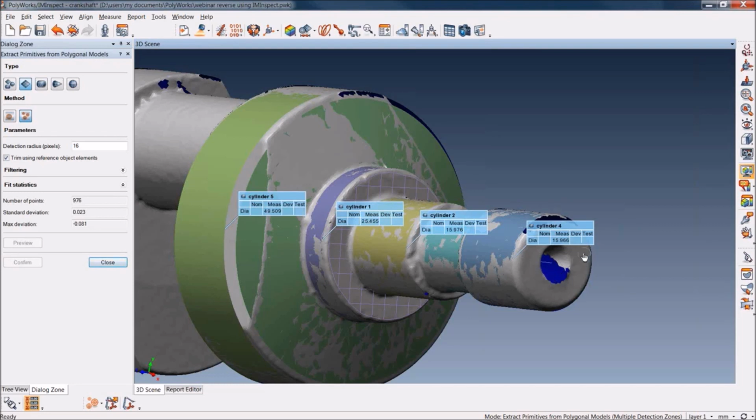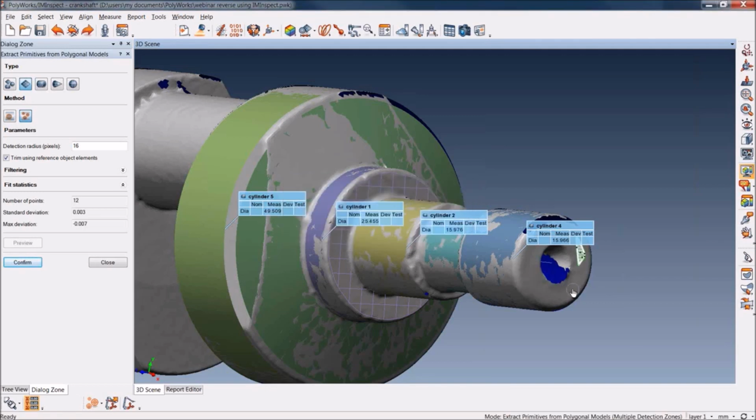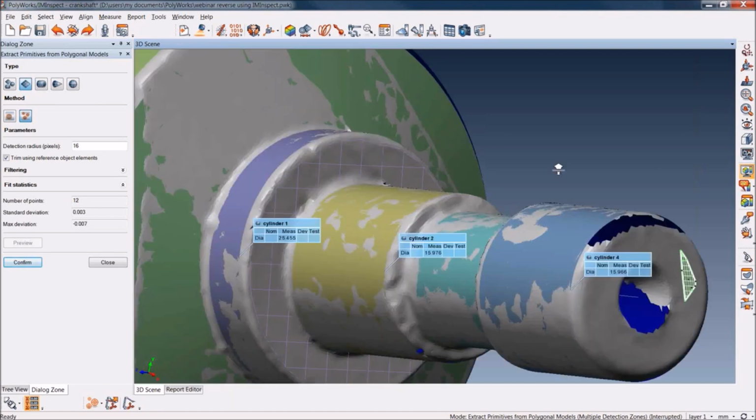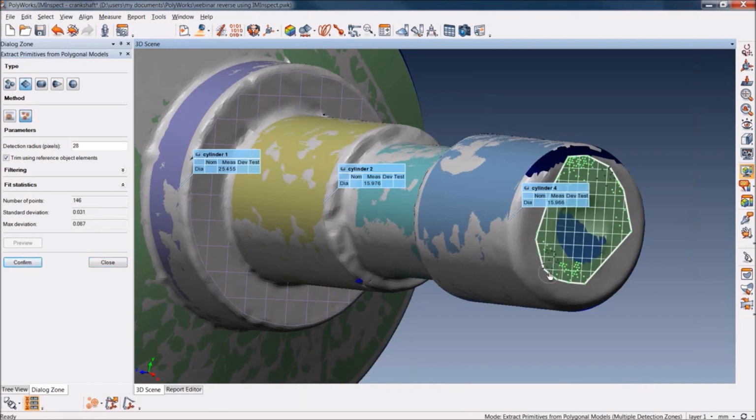Again, we can right-click and continue adding more in. So with multiple selections, we can fit those certain items. Now, if you want to delete selections of elements, you can middle-click. What that will do is delete each individual one as we go back. So if I zoom in and I middle-click one more time, it takes me back to the beginning. If I do a selection right here where I can refine it a little bit more, that gives me something more along the lines of what I was looking for, and we're going to go ahead and select that.